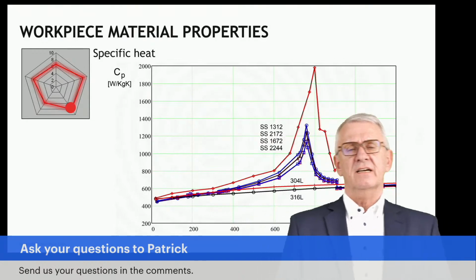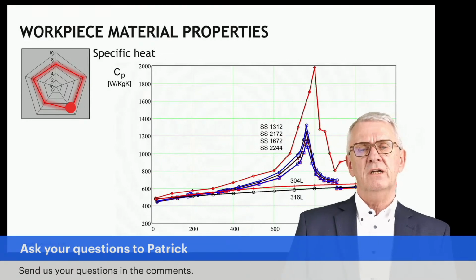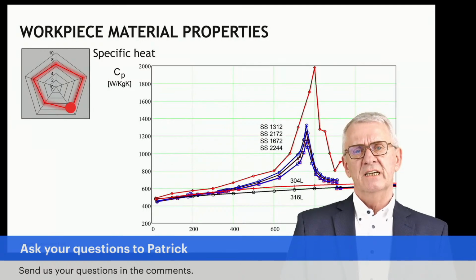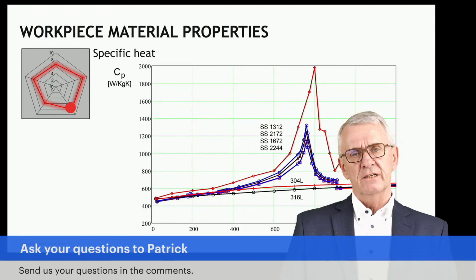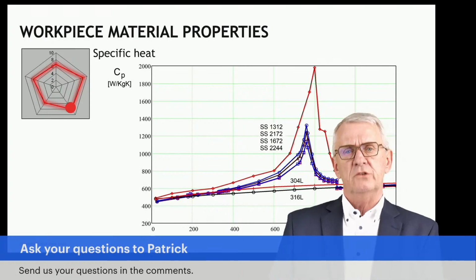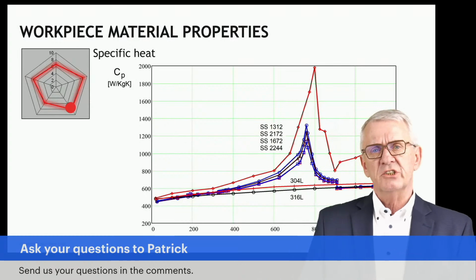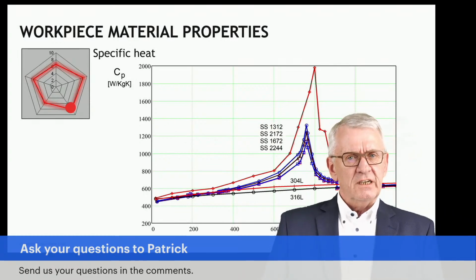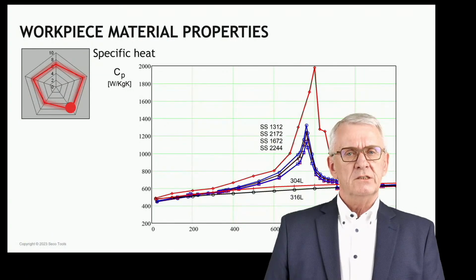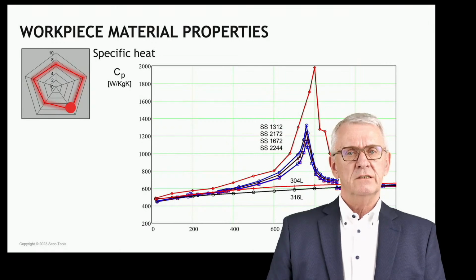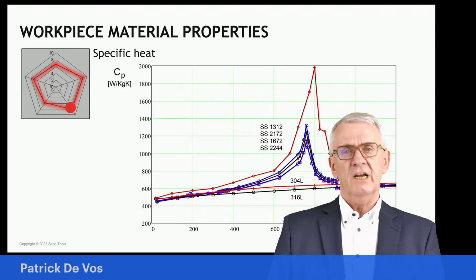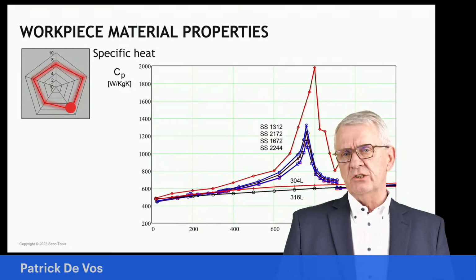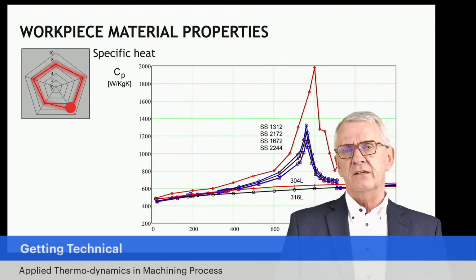And the red line peaking in the diagram is a typical line for iron. If you put heat in iron, the temperature increases. And the more heat you put in, the more the temperature will increase. But the higher the temperature, relatively seen, the even more heat you need to put in to increase the temperature by even 1 more degree. And somewhere around 800 degrees Celsius, and by the way, it's the same 800 degrees Celsius I was talking about somewhere in the beginning of this presentation, that's a coincidence, but anyway, the amount of heat needed to increase the temperature by 1 degree more is very high.